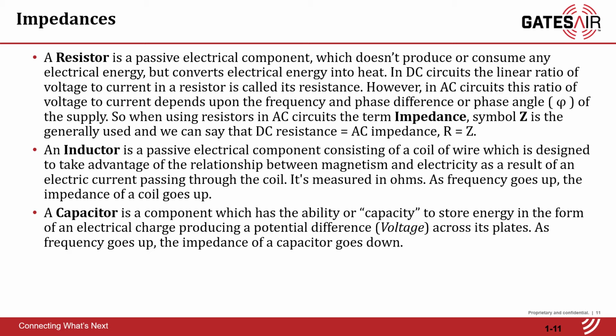A capacitor appears to be an open to DC. DC cannot flow through a capacitor, so it has a high impedance. As the frequency goes up, the impedance in a capacitor goes down. The capacitor stores energy between its plates.